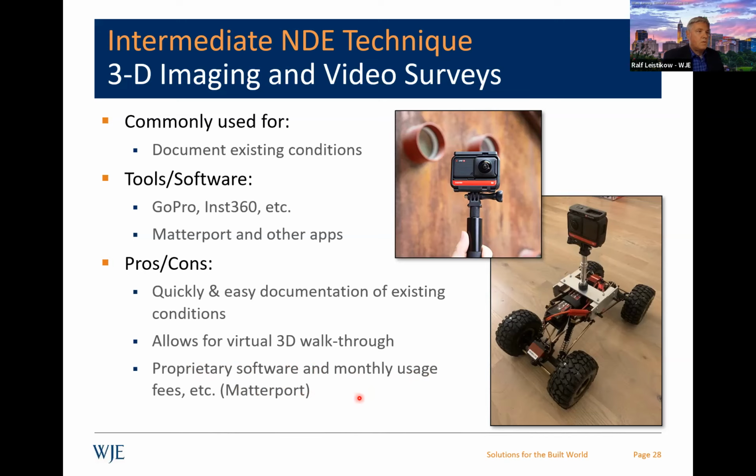But there are other vehicles to use for this. We can use this in combination with drone footage, where we can mate these together, and we can do 3D imaging and virtual fly-throughs. Basically you take those images and we actually use it to do quantity takeoffs potentially. You can look at concrete spalls and such on the images, map them out, and then use the software to actually get quantities.